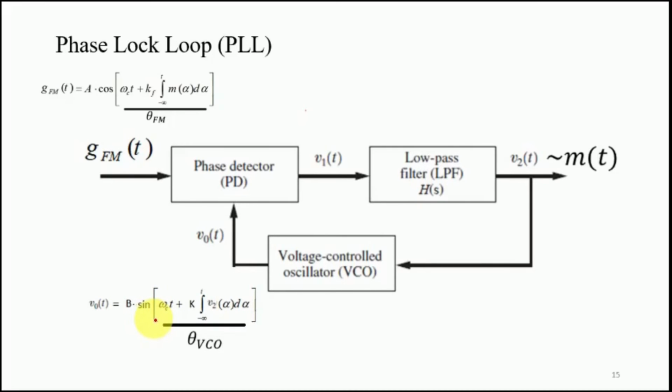So there must be a phase difference of 90 degrees between the two, which is ensured by means of the cos and sine functions. The free running frequency, which is omega_c, of the VCO is as per the carrier frequency by means of which we originally modulated the FM signal. Also, instead of the sensitivity parameter Kf, we have a constant gain K, which would depend on the gain of the phase detector as well as the gain of the low pass filter.